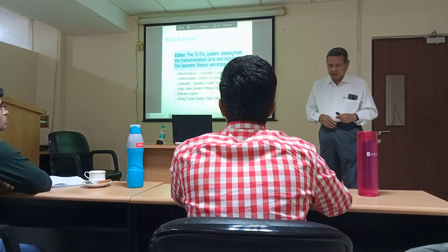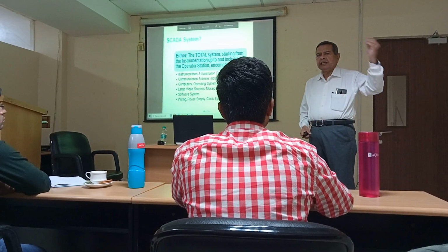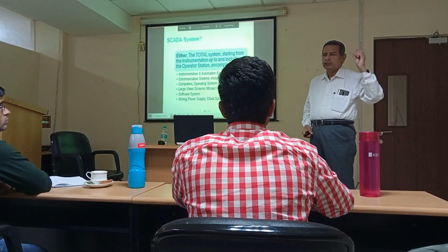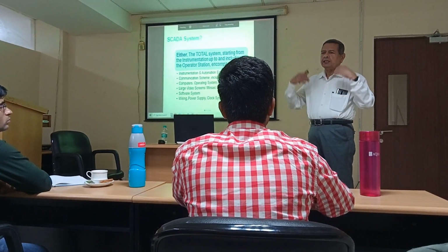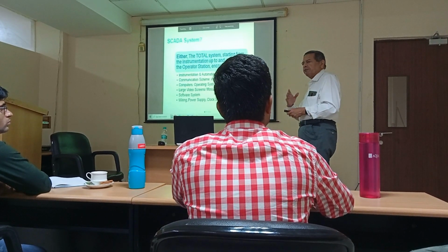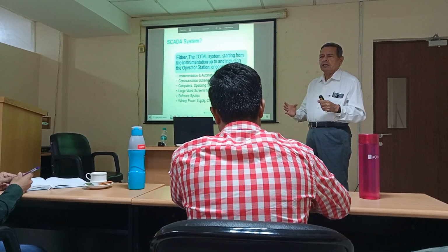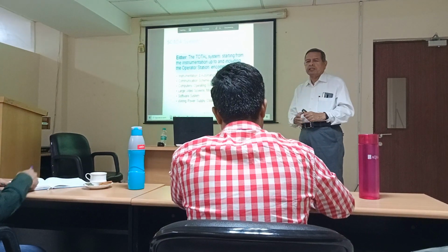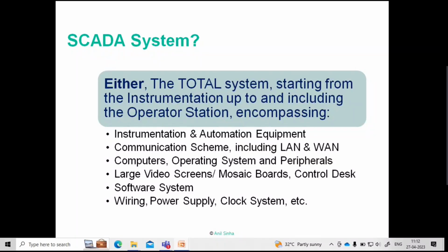Now, SCADA: the data will come from the end devices, the last device which needs to be monitored or even controlled, both ways. So that could be at a distance already. Starting from there, SCADA applies to everything right up to the control room. So the equipment system, including the operator, everything in the control room is definitely part of SCADA. But also the mechanism which you utilize to get data from far-flung locations. Even that is part of SCADA from my point of view.